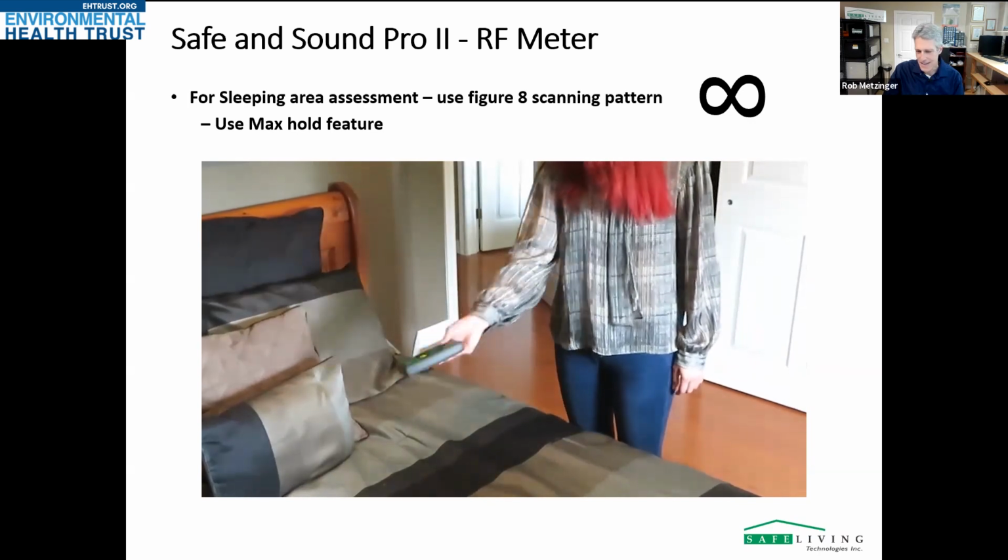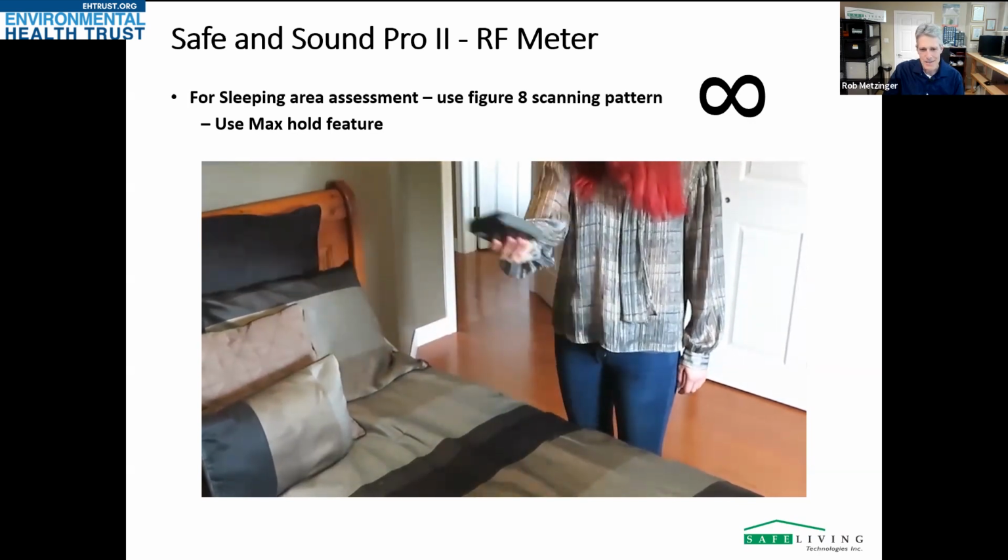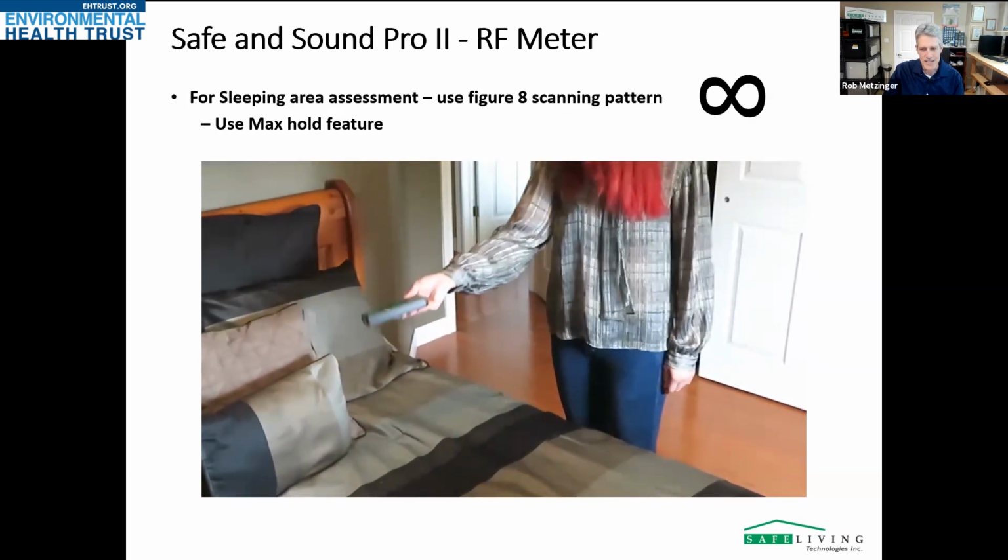And then that'll give you your exposure in that sleeping area. That's kind of the methodology we've developed in building biology, and that's really the kind of way you have to use this meter in order to do a surface scan of a sleeping area.